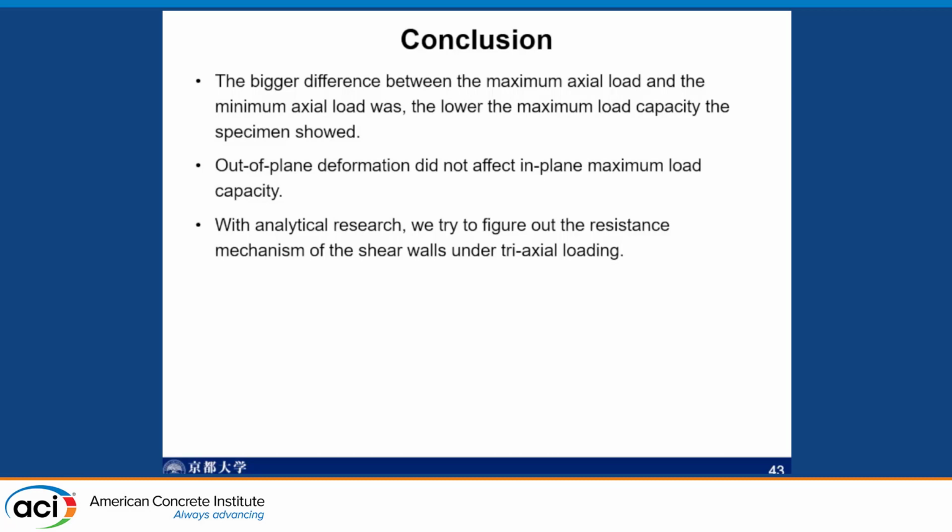So, you know, the shear failure may occur at the drift ratio of 1/200 or 1/250 in the in-plane direction. And then in the out-of-plane direction, we assume that we had a moment frame or moment resisting frame.